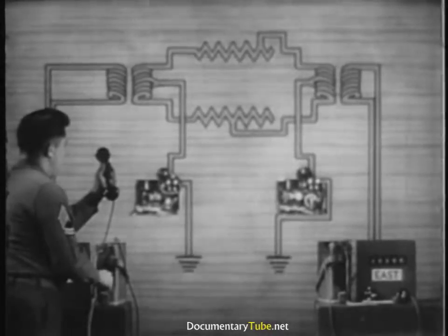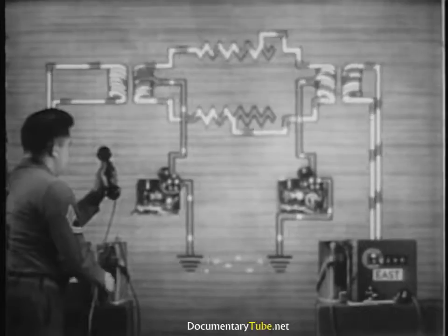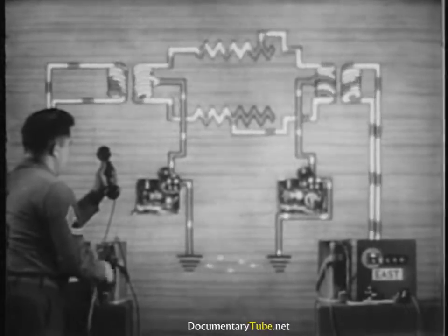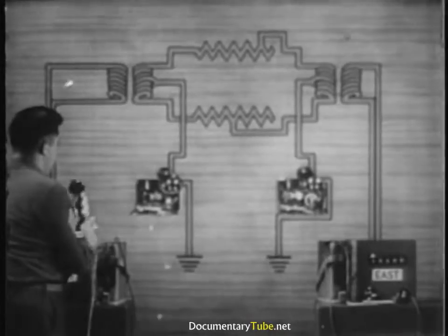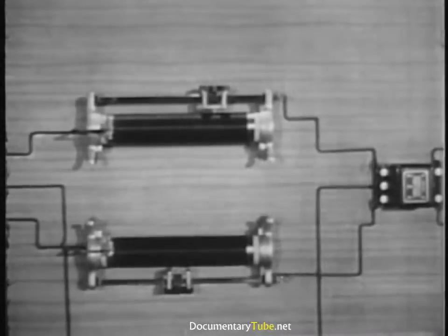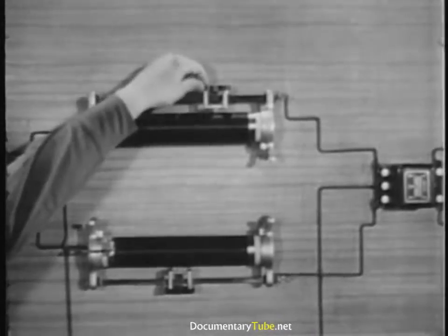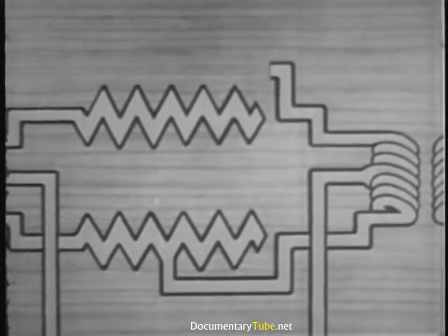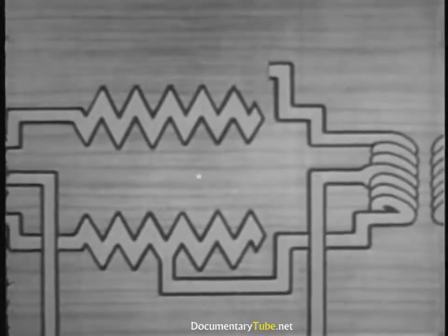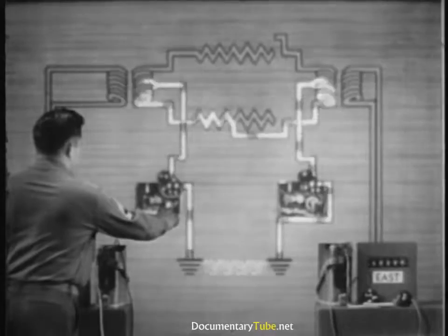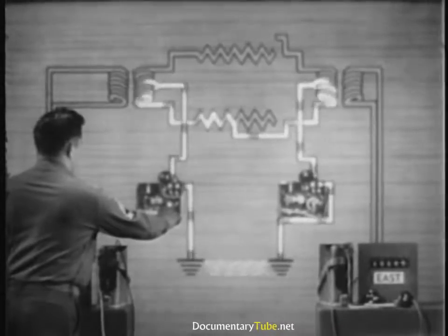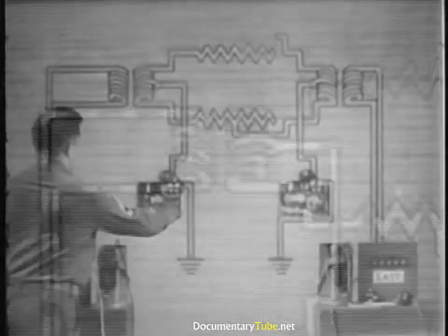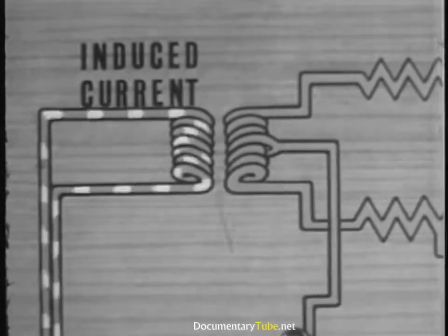And both ringing and voice current get through without interfering with the telegraph. The extreme condition of this unbalance occurs when one line wire is open. Now, all the telegraph current travels over one wire. And the current induced in the telephone circuit is at a maximum.